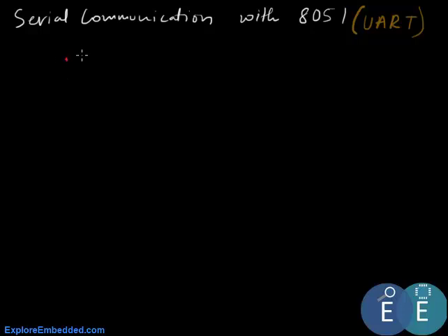So, this is used in, if we take an 8051 chip or a microcontroller IC, in order to debug or at times in order to transfer code from the computer to the microcontroller, we use this UART communication.